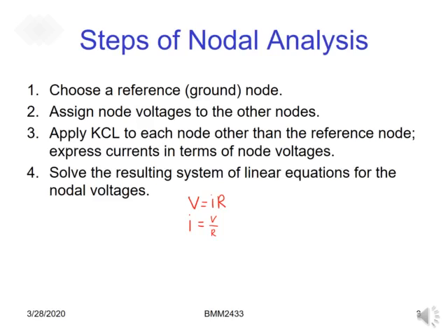So basically, the principle of nodal analysis is to apply the Kirchhoff current law. If you remember, the Kirchhoff current law states that the current entering the node is equal to the current leaving the node. And based on Ohm's law, we can express the current as equal to voltage divided by the resistance.